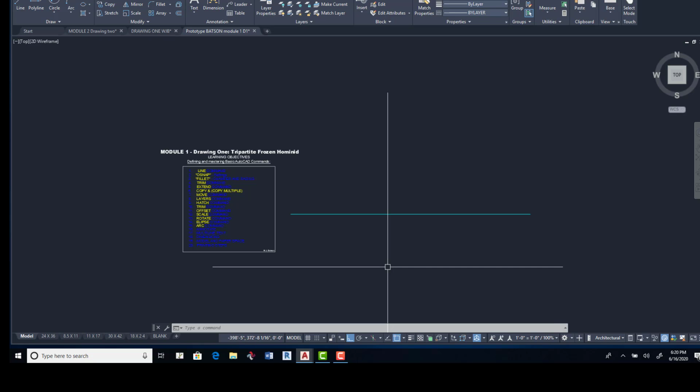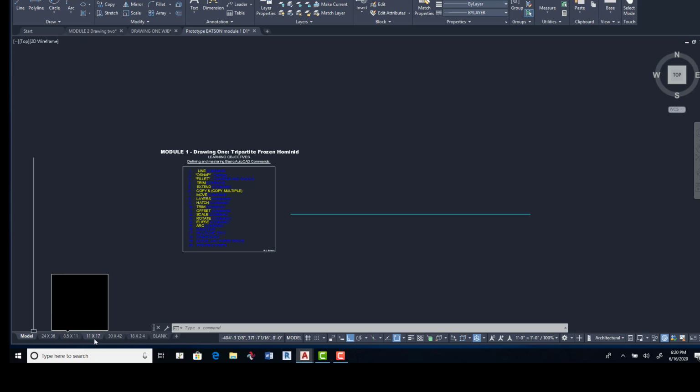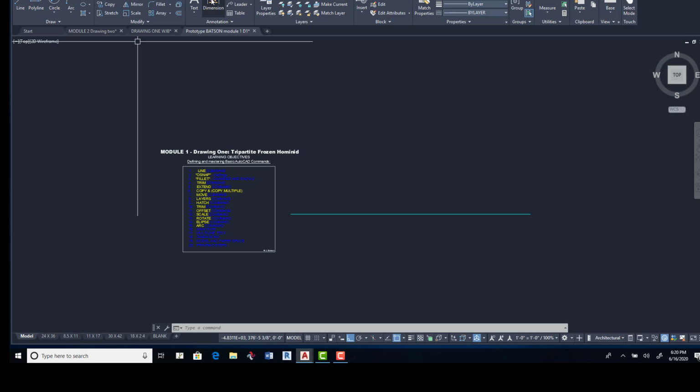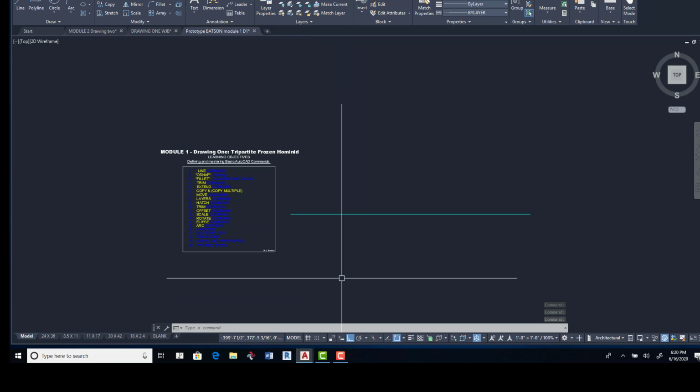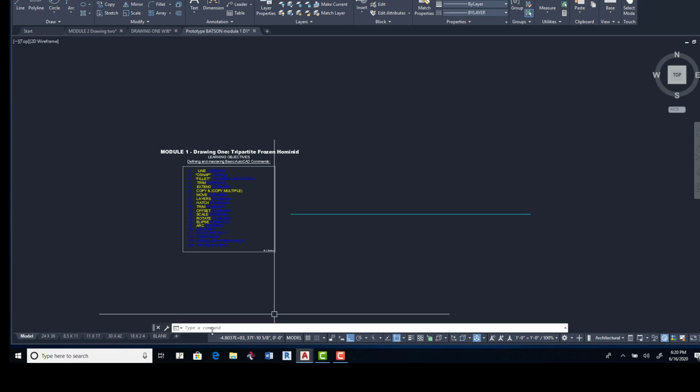And remember, you're opening up your prototype to save as drawing 1, save as drawing 2, save as drawing 3. So this is not a new file. So you should actually open up your prototype and clone it so that all of these model and tabs will be there, and all of these layers will be here. If you don't see the layers, that means you forgot to open up your prototype. These layers are only in this prototype that I've created, and these tabs are only here.